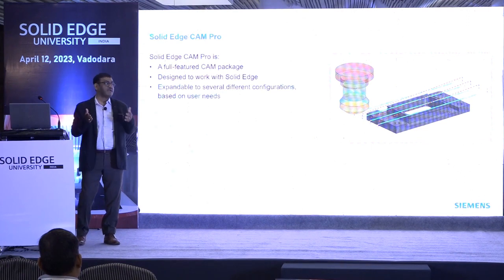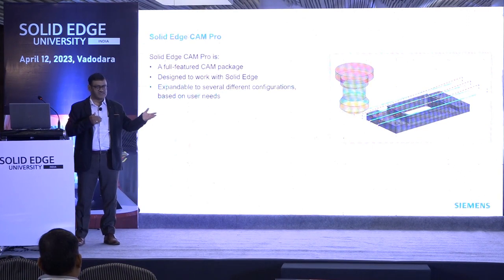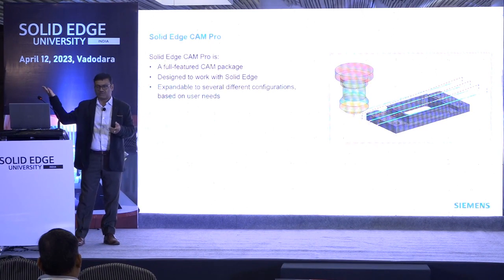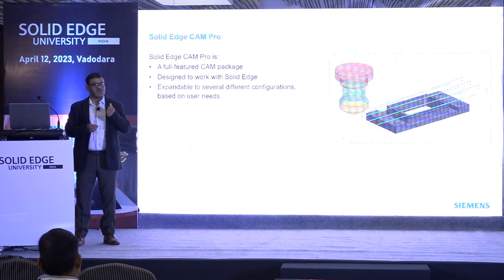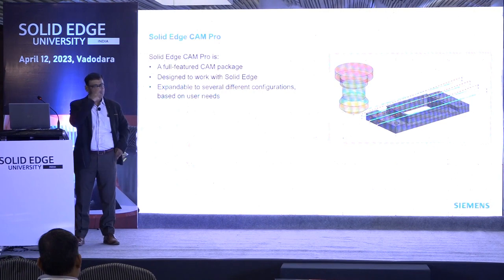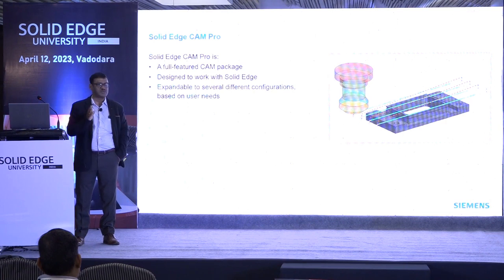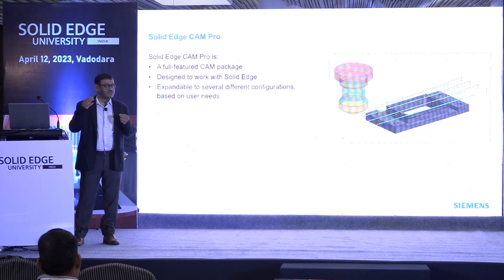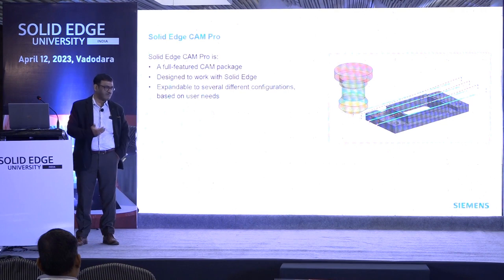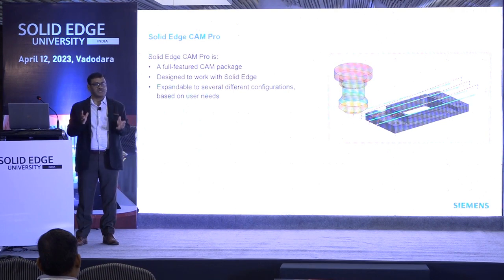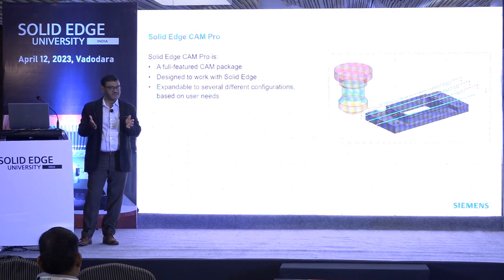But it is not just limited to that. When I say if a design changes, the manufacturing changes. But let's say you want to adopt a model-based definition, which he was talking about, PMI. In that scenario also, you have what we call link to PMI. If all the PMIs are already available in your design, you just have to right-click and generate the toolpath. Because in the backend, we have something called a feature-based machining algorithm, which will generate the toolpath. Right? So that's the architecture we have developed, so that MBD is not just a process, but brings downstream benefits.